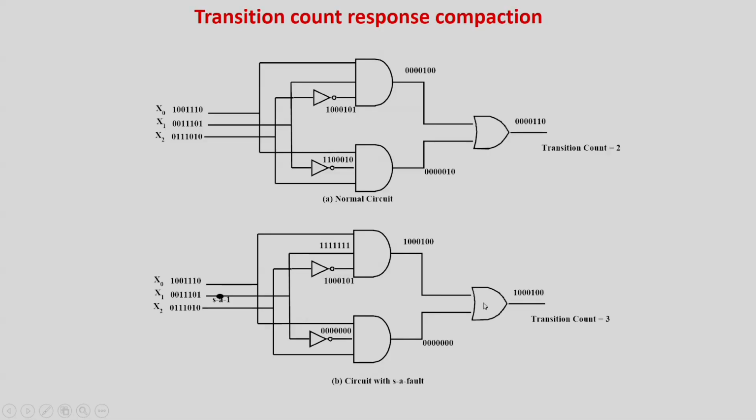I cannot have a very large area and explicitly store all of them and get zero aliasing and very good results. That is not actually allowed in BIST, because in BIST everything is inside the chip and you cannot make your tester circuit larger than the circuit under test itself. If your tester circuit is much larger, then the probability of occurrence of faults in such circuits also increases. The statistics say that if the circuit is large, the probability of faults becomes larger. But if you have a smaller circuit, you can design it with much more spacing between the vias and the wires, and have a slightly lower probability of faults. Even without any tweaks, a smaller circuit is going to have fewer errors.